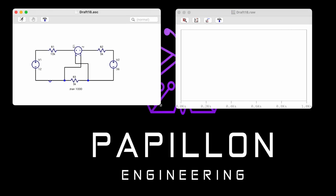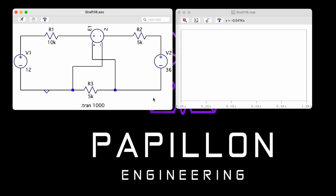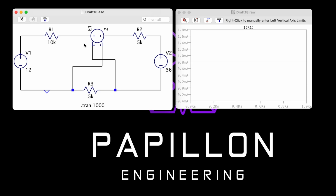So now we can take a look at the currents of the circuit. It's a series circuit, which means we expect the current to be the same everywhere. And we're also going to look at the voltage, but first let's look at the current. The current's 0.8 milliamps. I'm checking the current at the 10K, at the 5K, and at the sources, and they should all be reading 0.8 milliamps.